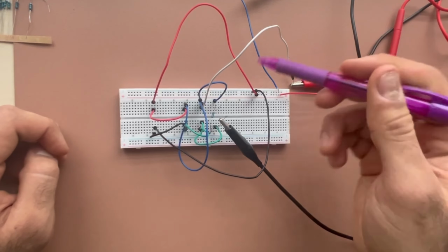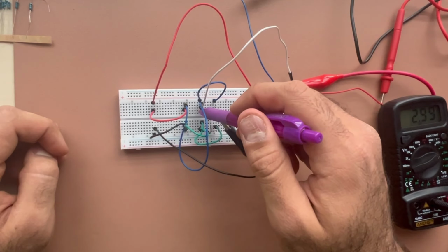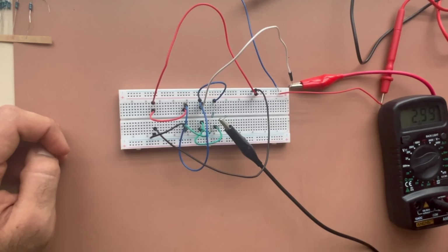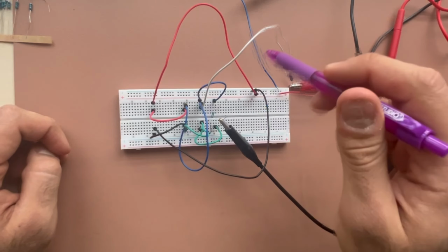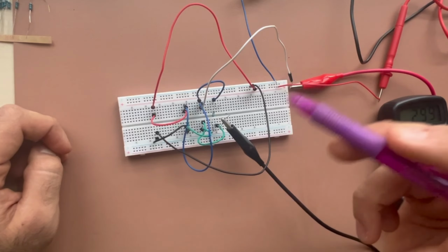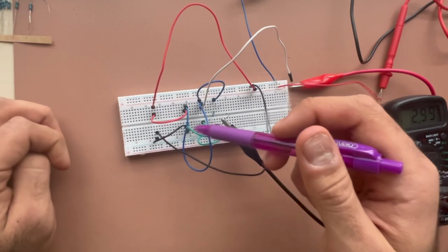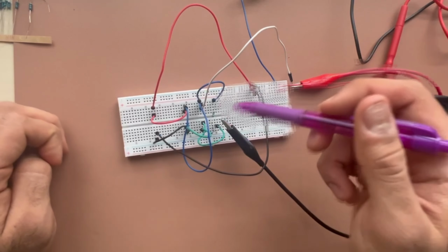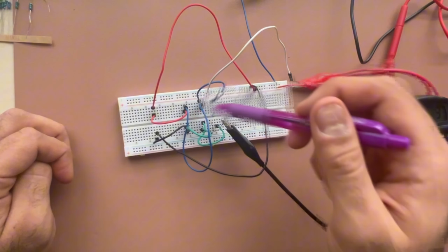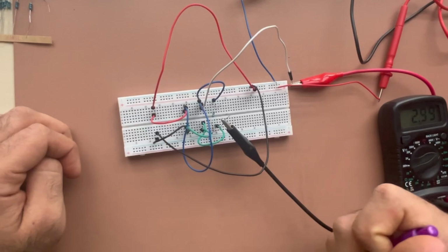In order to solve this kind of case, while you do have other components on your right side, it would be better to use the third jumper and, instead of disconnecting these two, just connect it over here, and on that end, put your ammeter in between the wire, sometimes node, and after that, the leg of your resistor. Obviously, you guys know how we can do it with the next one. So the answer for the first one is around 7.5 milliamps. It doesn't matter if I do it or not, but again, we have to do it based on the third jumper. So be very, very careful about that.